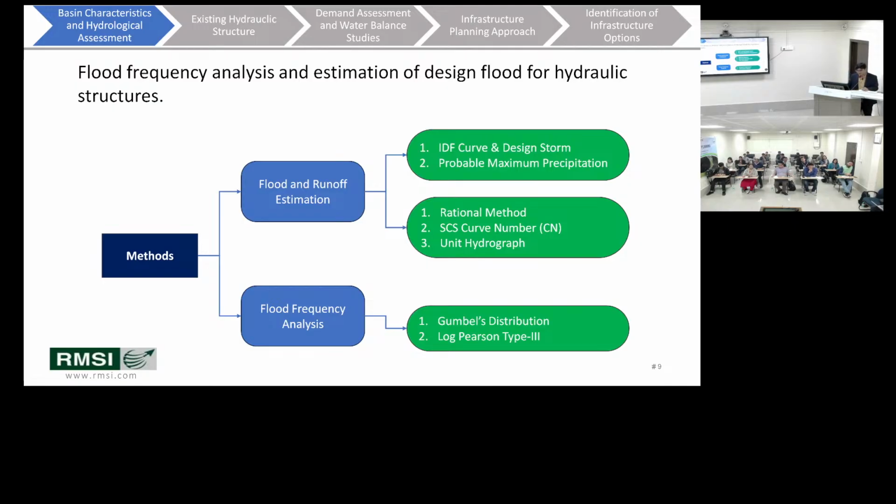period data you should have. Your estimation should tell you that if I am planning to design a culvert for this particular place to pass the flood, then you should have at least 50 year return period flood values in hand. And how to estimate the 50 year return period flood value? There are some standard methods. This training we have not considered, but we will try to highlight how to estimate the return period flood.